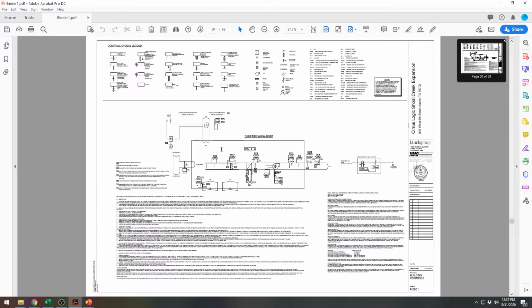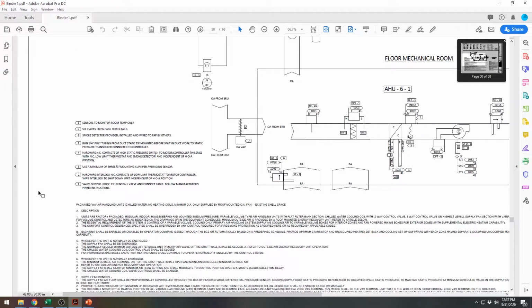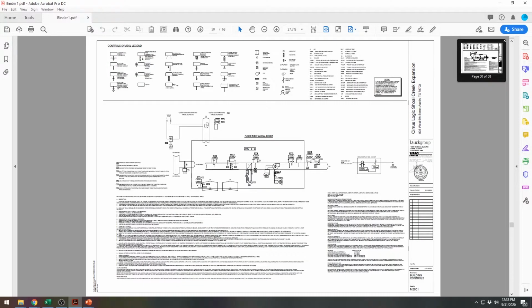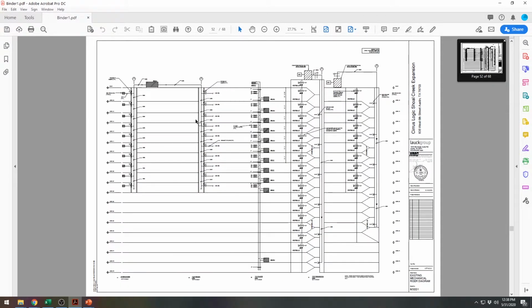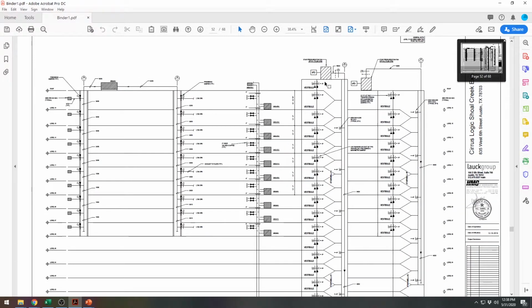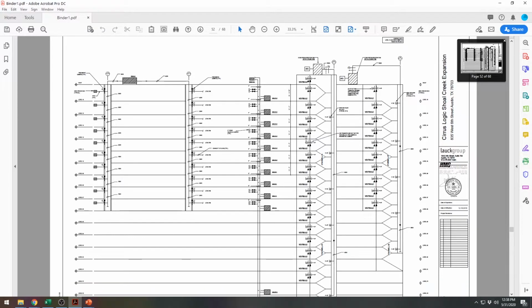Okay, then you have your controls. So your HVAC, they have some pretty complicated controls as well that measure temperature, humidity, basically sequence of operations. And in this particular building, and in most high rises, you'll have what's called a pressurized stairwell. This is in case of emergency. Essentially, they pump air into the stairwells to keep the smoke out. So this is how they control the air going into the stairwells to pressurize those in case of emergency.